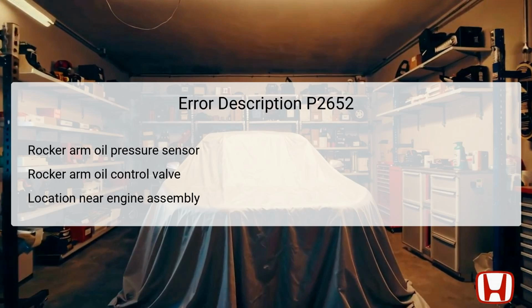When the sensor outputs high pressure unexpectedly, it signifies a potential fault either within the sensor itself or associated components like the rocker arm oil control valve that regulates oil flow. The rocker arm oil control valve plays a pivotal role in managing the oil pressure to the rocker arms, influencing the activation of the VVT system.